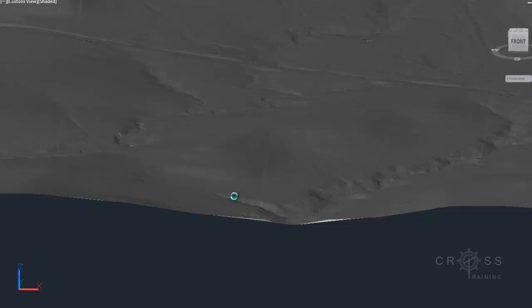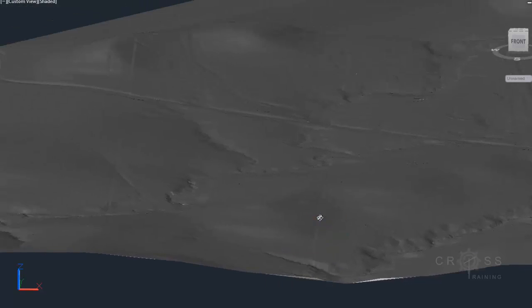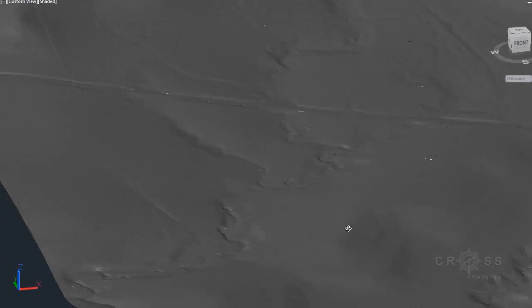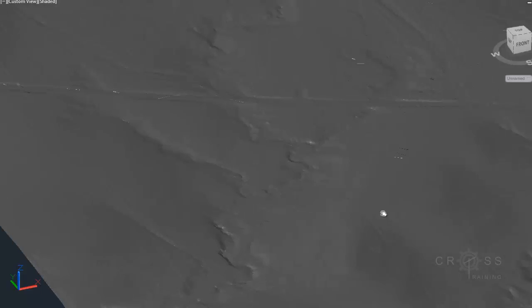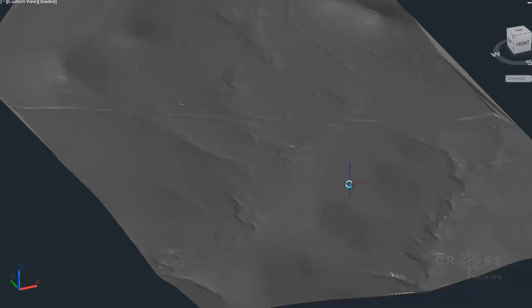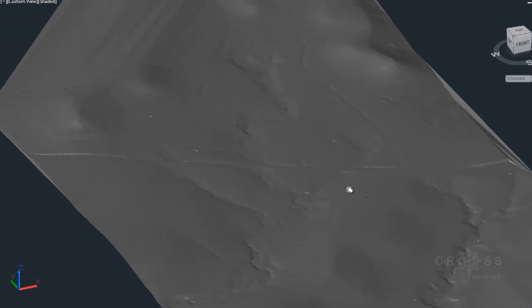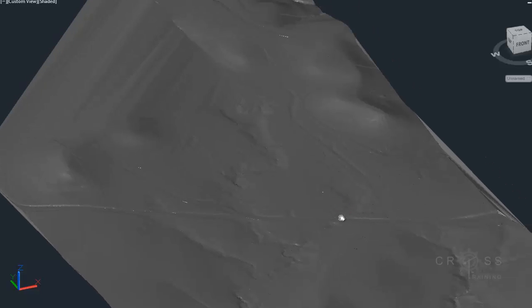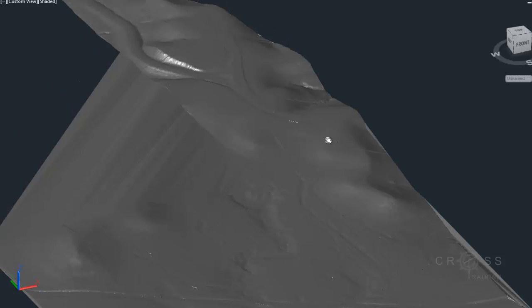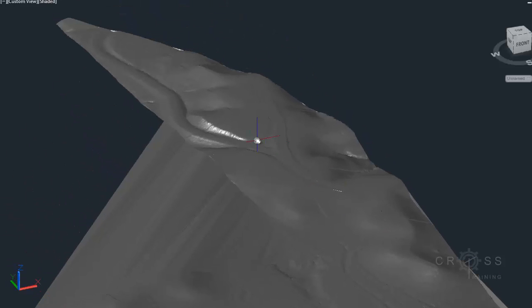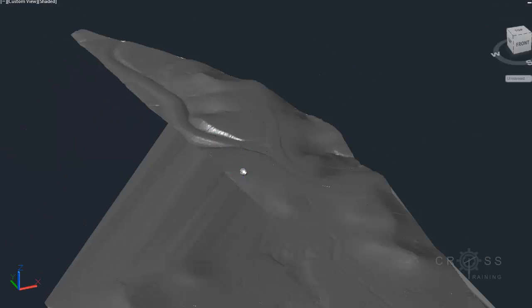And these contours were created from 2-meter LiDAR data in ArcGIS. So in ArcGIS we created contours from there, and we brought it into Civil 3D and built this surface from that. So we can see some of the high points here. Looks like we have another street running through here. So this looks pretty good other than our stray triangulation.